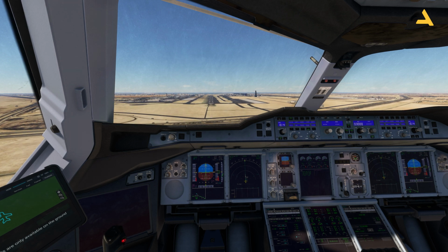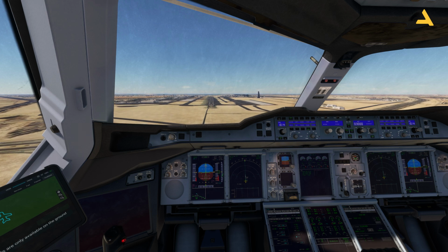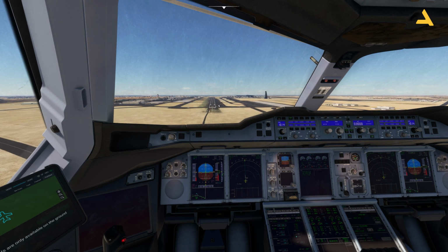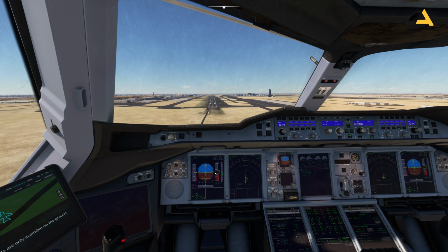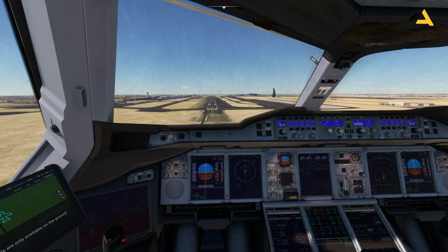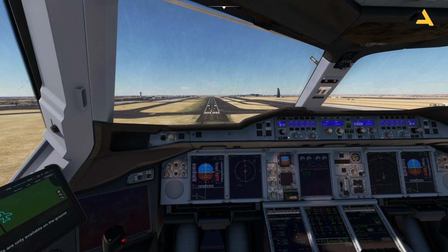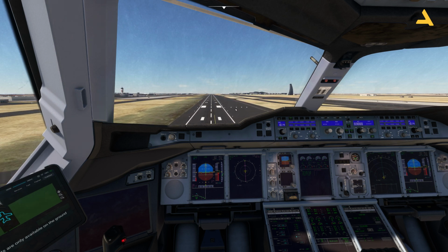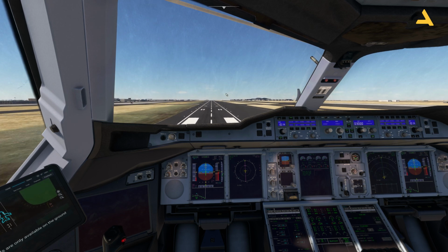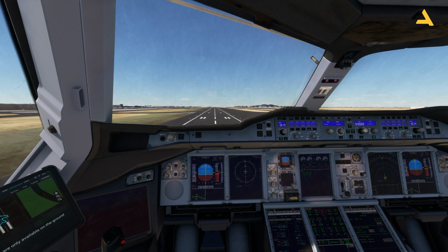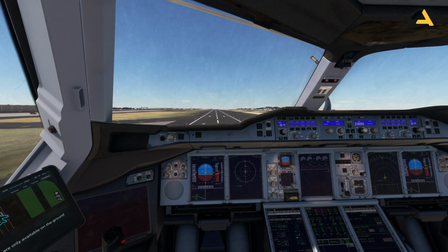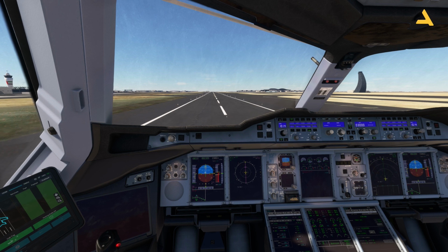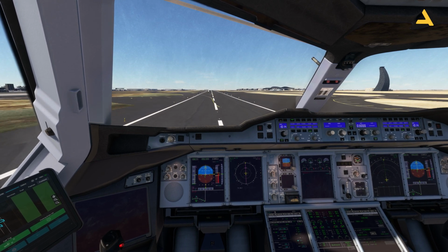Slightly high, as you can see, the PAPI lights, 3 are white, so it means the plane is coming in at a higher altitude, but it's following the glide slope. You can also have a look at it by turning on the LS over here. Minimum. So it's slightly high. 50, 40, 30, 20, it's high. 10, retard. Yeah, see, it didn't happen, so I have to do it myself. And now. That's it.